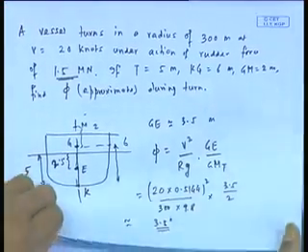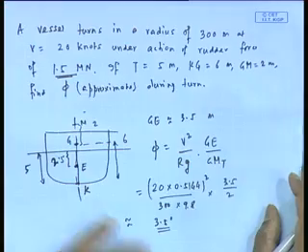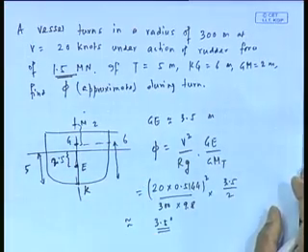Now tell me one thing. So like that we can work it out approximately. It is not much, 3.5 degree. Normally, the heel during a turn can be about 5 degrees, 6 degrees. It can maybe even be 7, 8 degrees or so. You can see some nice pictures. As I said, there is a very nice picture of this US aircraft carrier turning, and you can see it is heeling on the outside. And heeling outside is always more dangerous after all, because things will fall outward. If you fall overboard, you'll be falling outside the loop, not inside the loop.